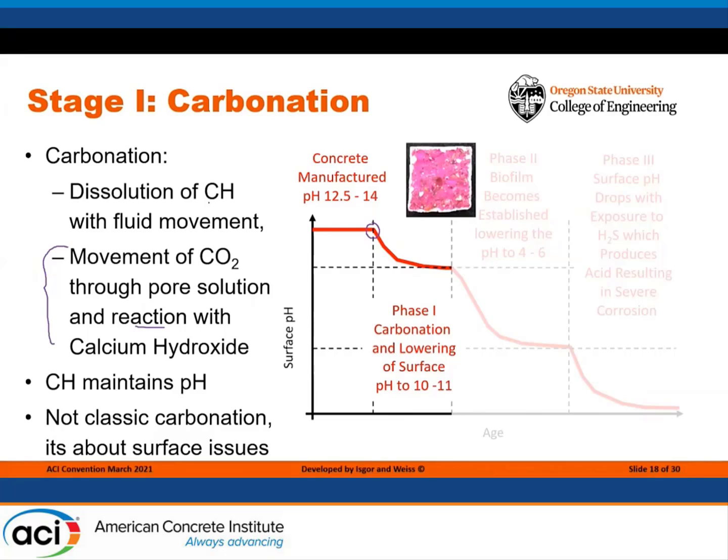The final thing I wanted to really mention here is this isn't classic carbonation where we worry about how many inches into our concrete the CO2 front is really propagating. Here, we're worried about really where the bacteria are going to come in contact. So we're dealing with a very much localized surface phenomenon. This can be taking place only within, let's say, the outer millimeter of the sample, because it's that outer millimeter where the biofilm is really going to start to attach. So this is very, very difficult to prevent.